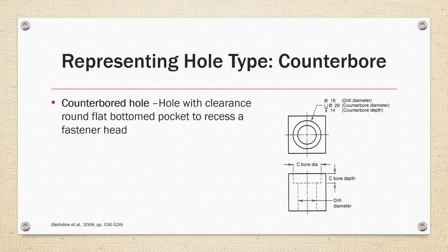The example in the image to the right is calling out a 29 millimeter counterbore with a 14 millimeter depth. The profile view should detail the counterbore feature using hidden lines as shown in the image.